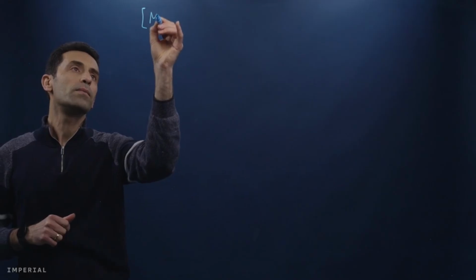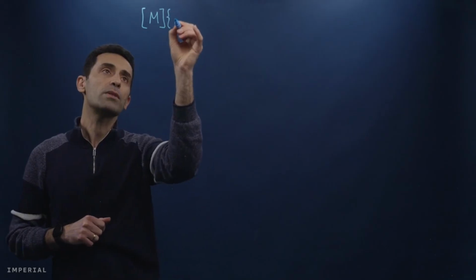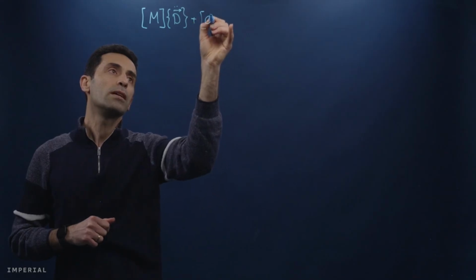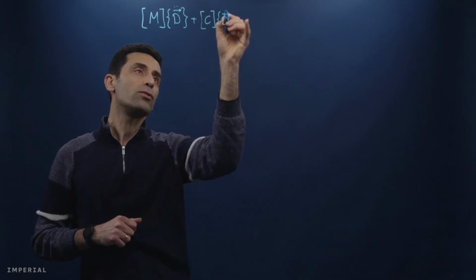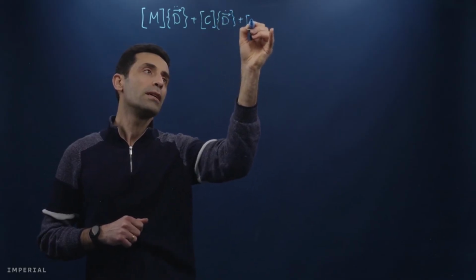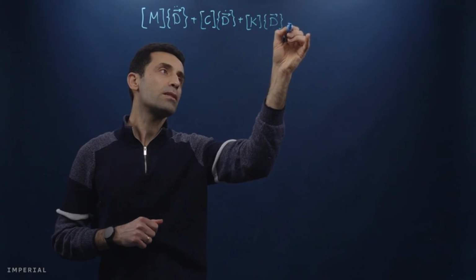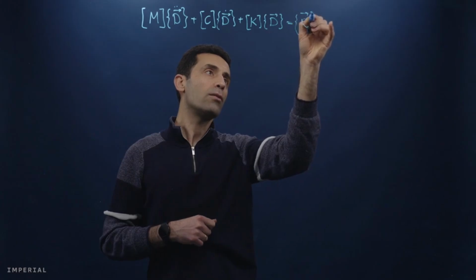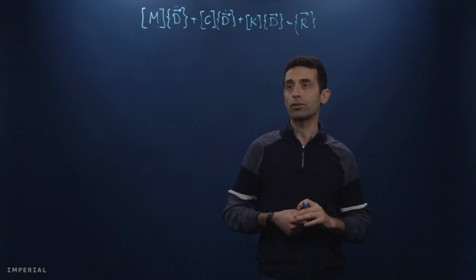That equation, just to remind you, was this matrix, which is the matrix of nodal masses times the vector of nodal accelerations, plus matrix of damping times vector of nodal velocities, plus structure stiffness matrix times vector of nodal displacements, equals all the external forces that are applied to our nodes. So this is our equation of motion in FE terminology.